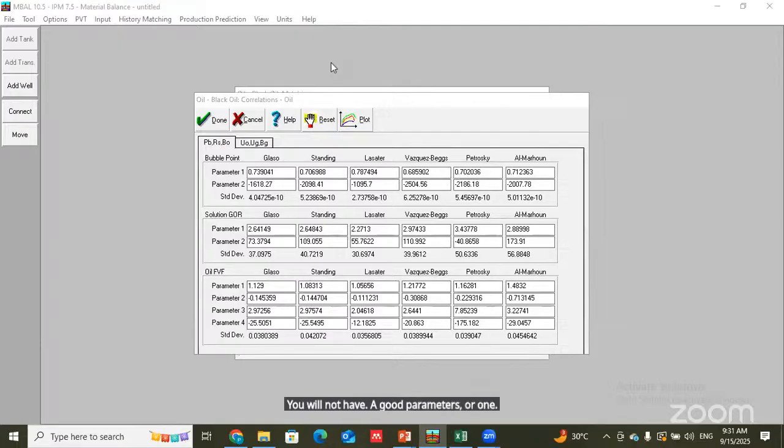Why is the bubble point constant? The bubble point is constant for each type of oil you have, unless you have a compositional gradient. Normal reservoirs have a single oil property. The bubble point is the pressure at which the first bubble of gas evolves from the oil.